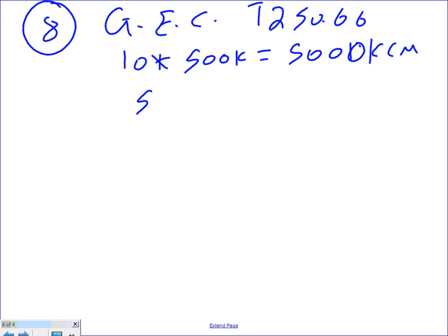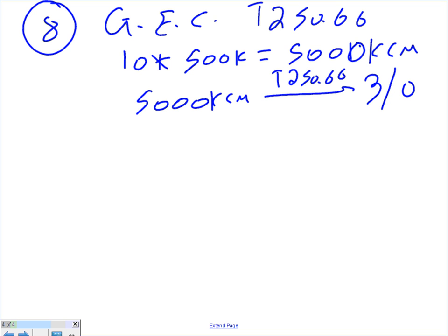You take the 5000 kcmil to Table 250.66, and right there it tells you the largest that you can pull is what? 3/0, right? If I remember right, the largest that you can pull, regardless of the size, is 3/0. Done. Exactly the same as the bonding jumper, except you stop at 3/0. You don't have to move anywhere else.